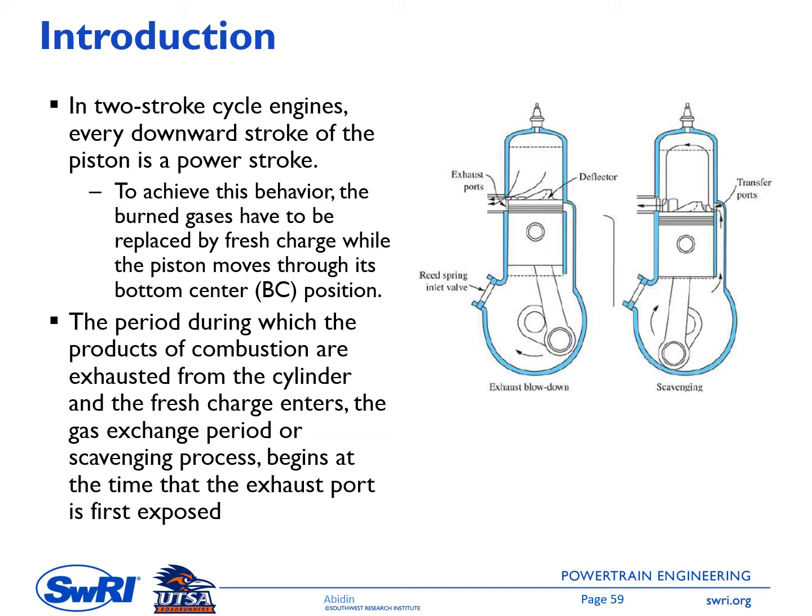This is the time where the exhaust port opens, and then the piston continues its movement toward bottom center. Bottom center will be somewhere here, okay? And then on the next occurrence, the transfer port, which is the port where the fresh mixture enters the cylinder, opens, and the fresh mixture will enter the cylinder chamber at the time the exhaust gas is expelled from the cylinder chamber. These two processes occur simultaneously. That's why we have to have a good scavenging process, to make sure that the entering fresh mixture helps scavenge the exhaust gas from the cylinder chamber.